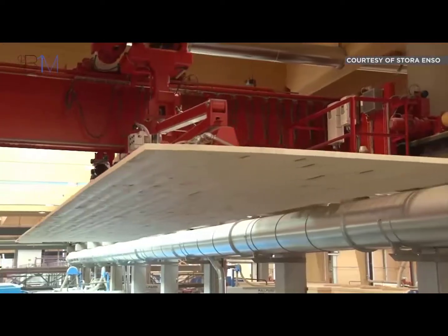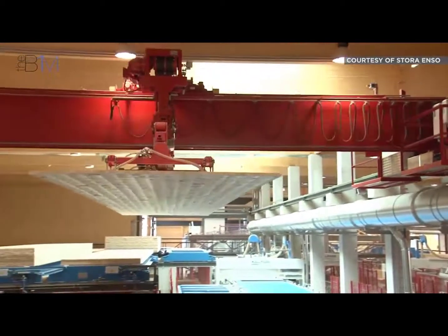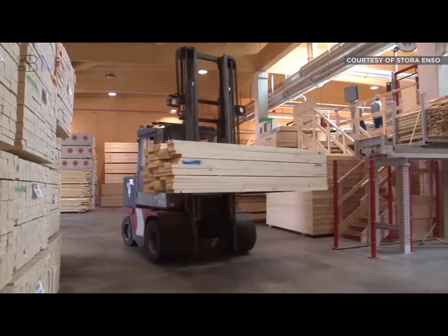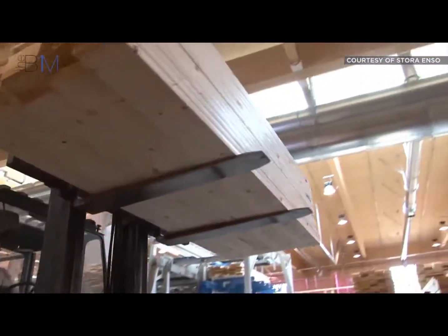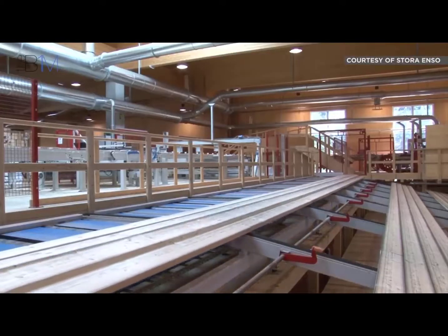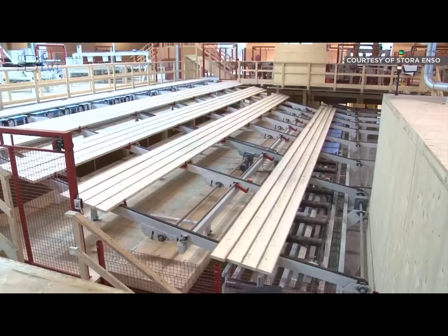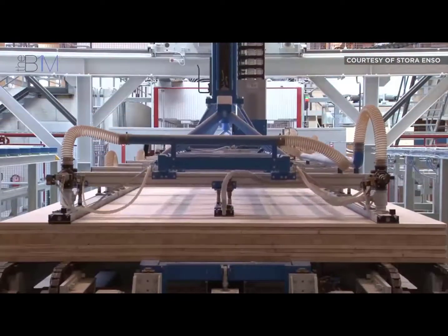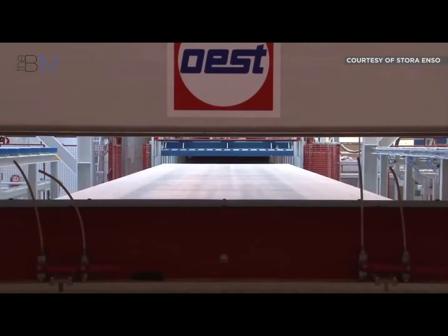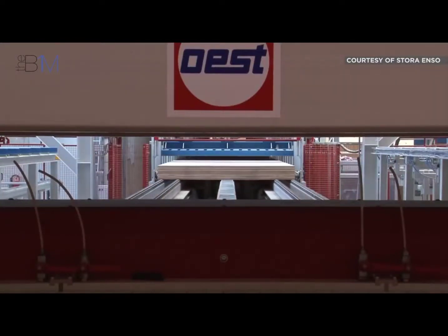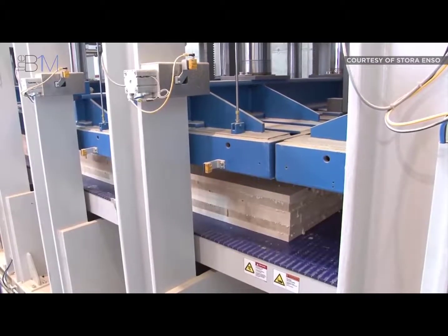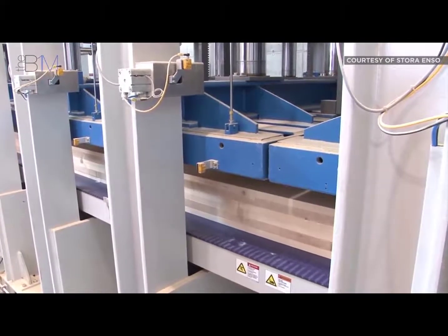Often referred to as super plywood, the material is constructed in a controlled factory environment from sustainably sourced timber. CLT is manufactured from spruce, although Scots pine, larch, and Douglas fir can also be used. Once at the factory, the timber is planed and then kiln dried to reduce moisture content. The conditioned timber is then stacked into layers, known as lamellas, on top of one another. Each layer is placed at a 90-degree angle to the one beneath. These layers are then glued using a non-toxic adhesive and hydraulically pressed together to create the high-strength structural panels.